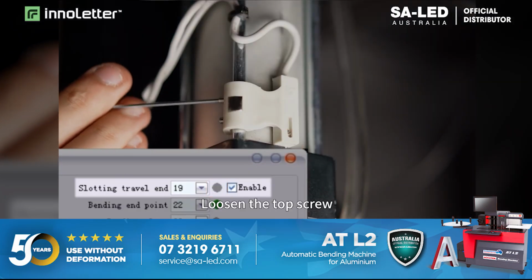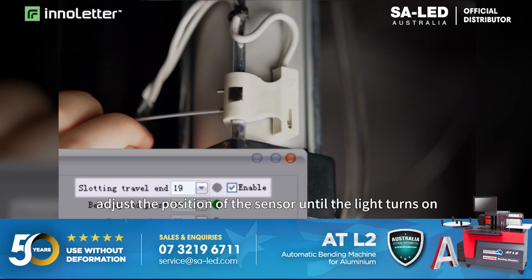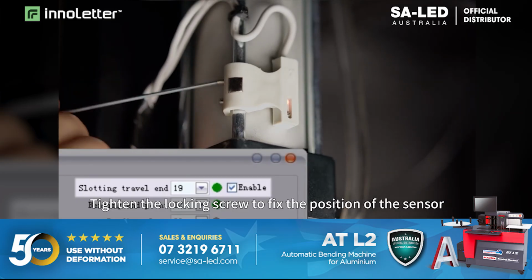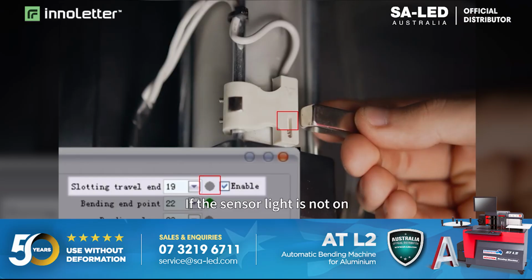Loosen the top screw. Adjust the position of the sensor until the light turns on. Tighten the locking screw to fix the position of the sensor. If the sensor light is not on, the corresponding port does not respond, indicating sensor failure. It needs to be replaced in time.